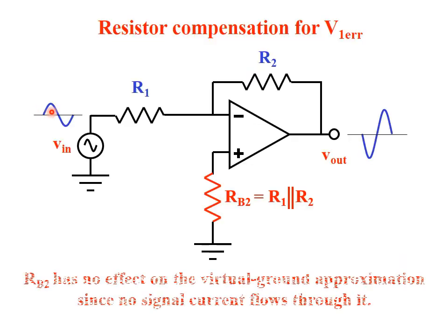You see the input and the output. The output here in the inverting amplifier is amplified and it's inverted. The positive will become negative and the negative will become positive. That's why we call it an inverting amplifier. So if the input voltage is negative, the output will be amplified and positive. If the input is positive, the output will be negative.